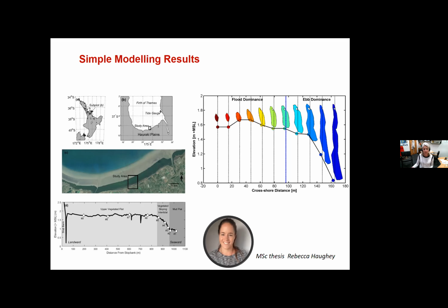Well, it was a full model, but she extracted a profile from that and plotted out these tidal stage plots as you moved from outside the intertidal here over up the fringe, and then as the colors go red, right into the center of the mangroves. And she could show that at the top of the intertidal, the currents were flood dominated, and at the lower region, they were ebb dominated. So that was the classic shape of the tidal stage plot over one of these intertidal areas.